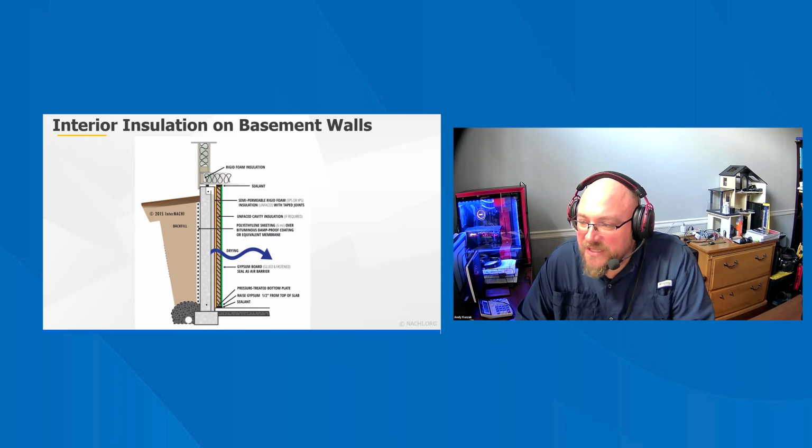If a basement will only be insulated and not finished, a fire-rated foam panel or similar fire-rated covering needs to be used. Because above-grade portions of the basement wall can dry to the outside, fire-rated insulation on these surfaces may be of an impermeable type. For example, it can have foil facing, but insulating approaches that restrict the drying potential of below-grade portions of the foundation wall toward the inside should be avoided.